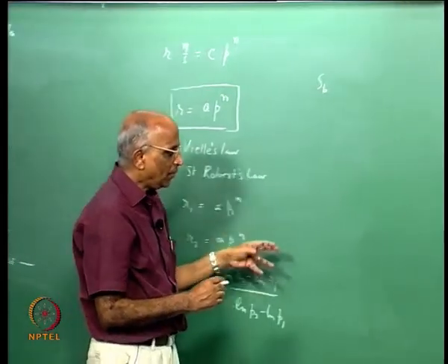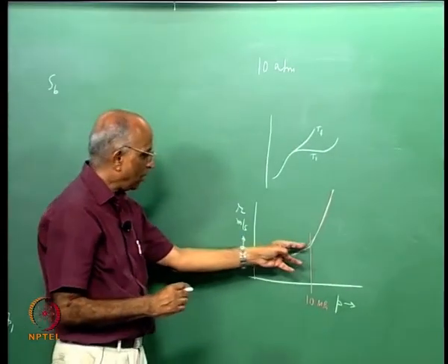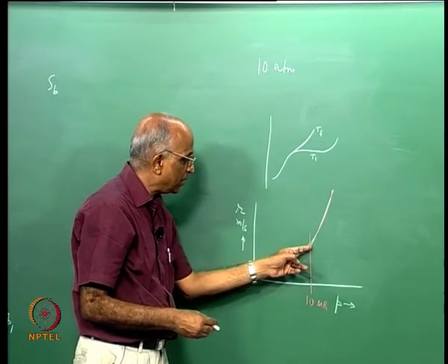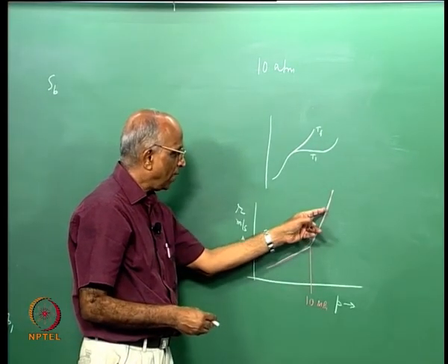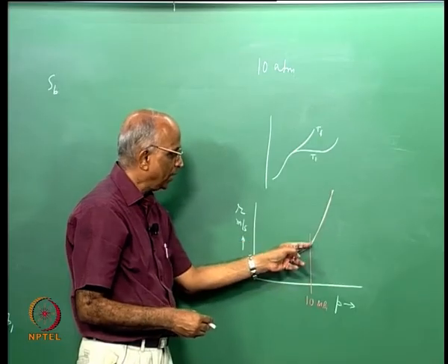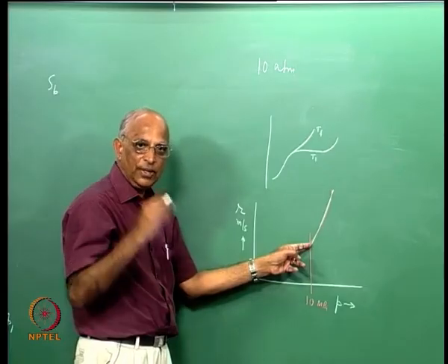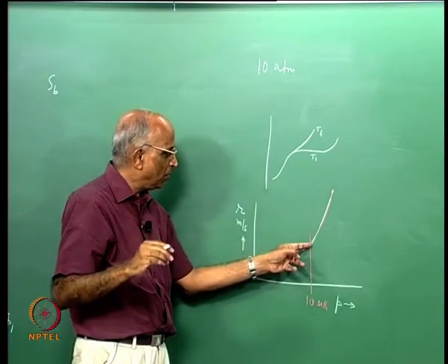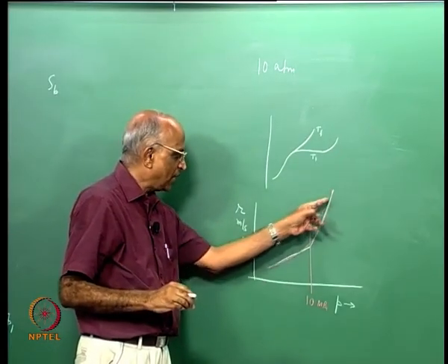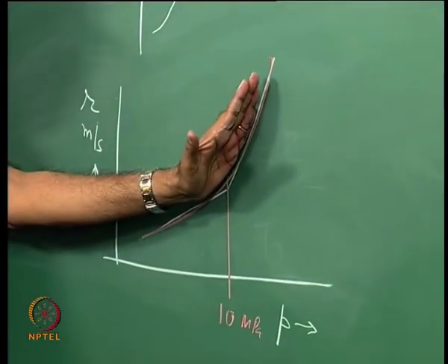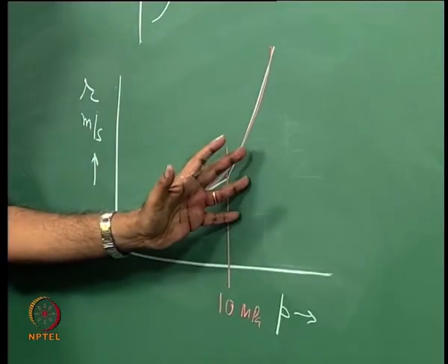Thereafter, we said that when the reactions happen directly at high pressures, that means instead of having a dark zone you do not have that, temperature increases from surface temperature directly to the flame temperature, more heat gets conducted, therefore n is higher. So you have a small n followed by a large n for the double base propellants.